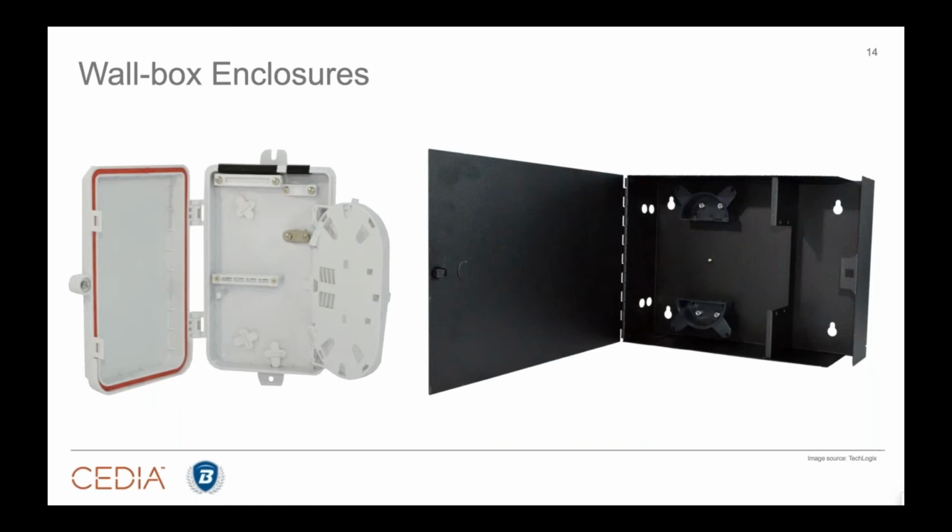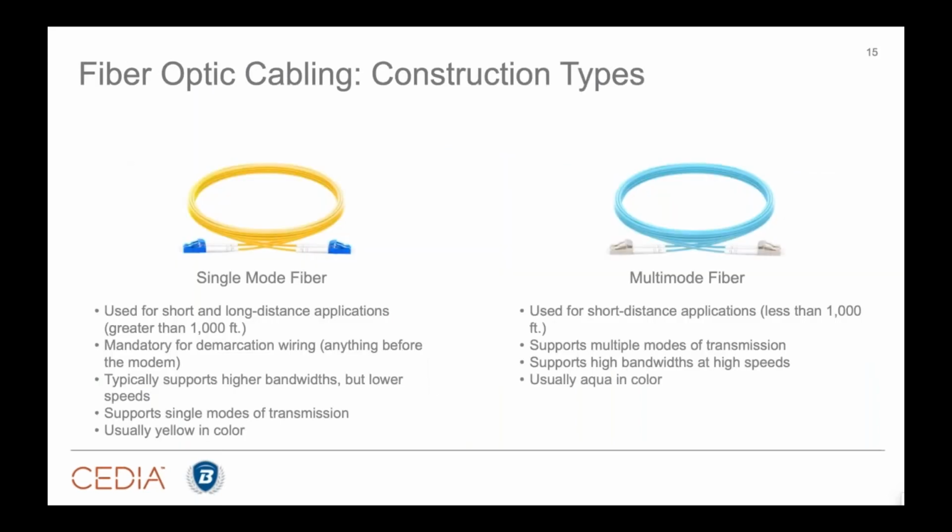They start around $50 trade price. They'll make sure you have service loops, so extra fiber. If you're going to break fiber in the field, usually you're going to break it at the connector. That's where you're going to see the damage, and you have extra fiber to fix it. Or you have the fiber strands properly secured so those lasers fire properly. We'll talk about that here in a minute. My advice to you: make sure you get enclosures, make sure they become part of the design.